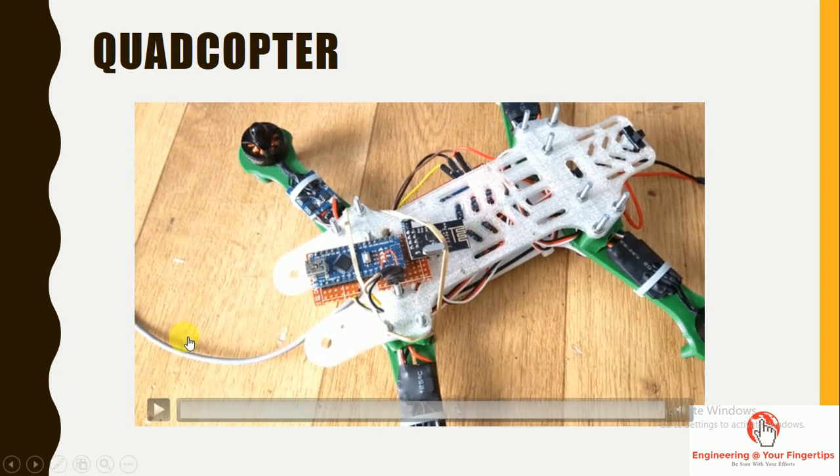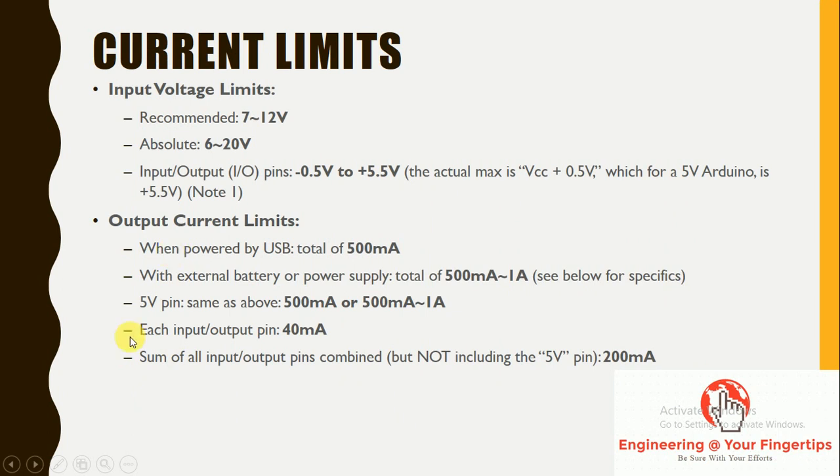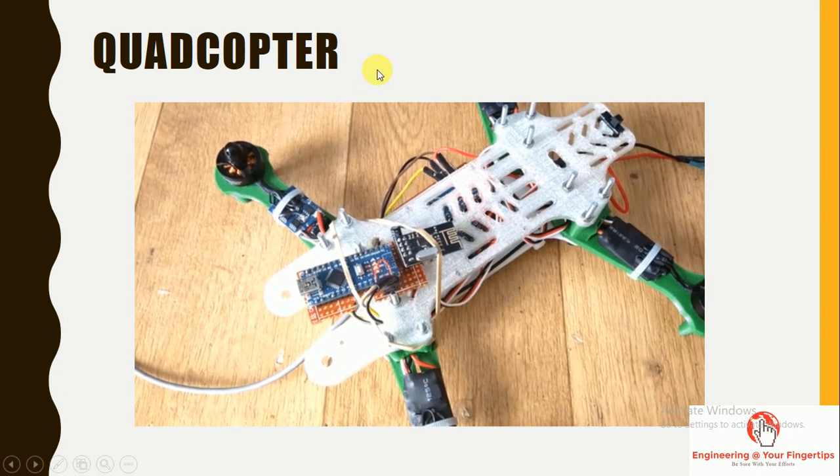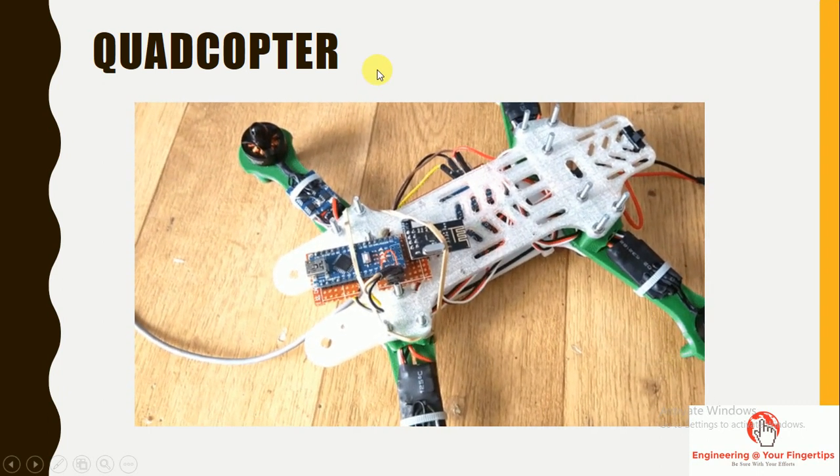So you need some other power supply. Like on a quadcopter, there is a big fat battery on the bottom, and that is the power supply. The Arduino that we use to drive the motors doesn't actually directly feed power to the motor. Instead, the Arduino controls the switch between the big battery and the motor. So it controls access to the power in that sense. We will talk more in detail about this in future slides.